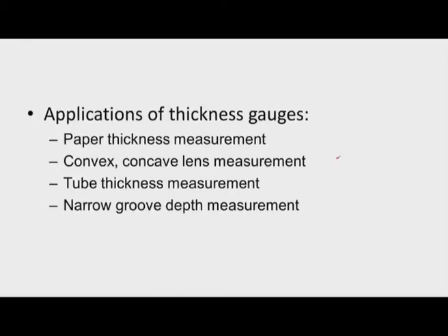For example, say we want to measure a convex lens like this. In that case we can use both a flat anvil and a flat spindle.